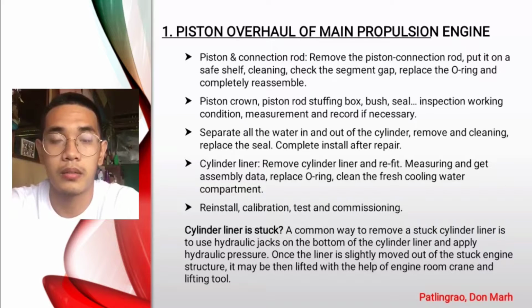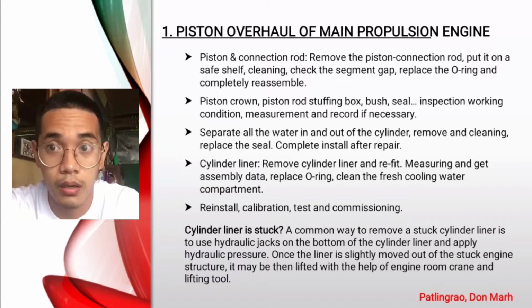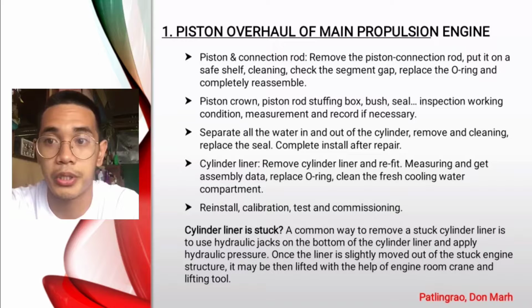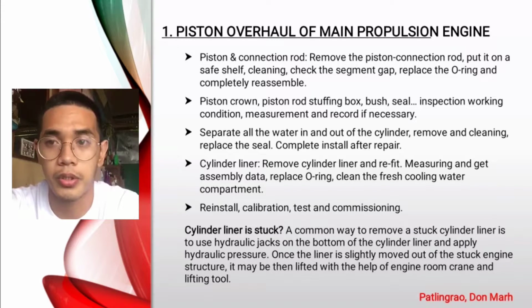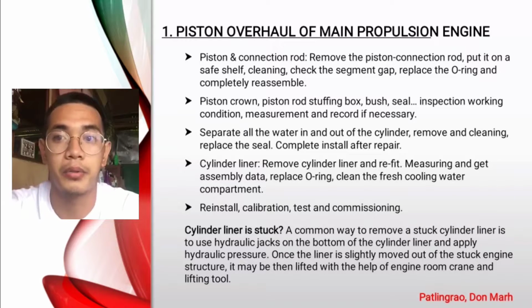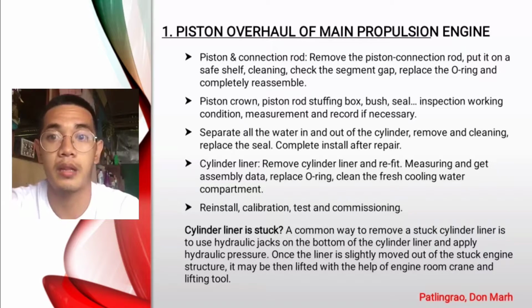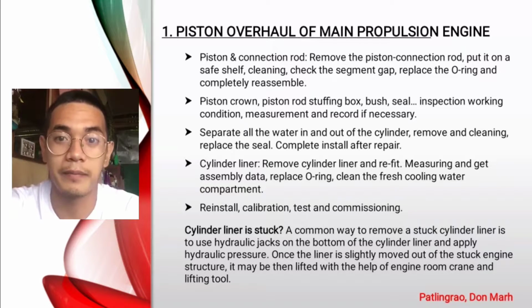So what is a cylinder liner? I just want to expound on what a cylinder liner is. A common way to remove a stuck liner is to use hydraulic jacks on the bottom of the cylinder liner, and the hydraulic pressure slightly moves it out of the engine structure. It may then be lifted with the help of the engine room crane and the lifting tool. That's it. Thank you and have a great day.